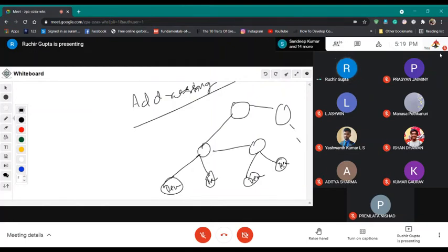Each device on USB, a hub or device, as I have told you, is assigned a 7-bit address. Importantly, this 7-bit address is local to this USB tree. So this 7-bit address is only known to this USB tree.